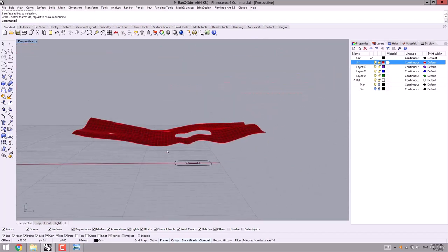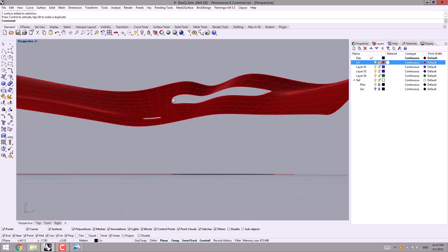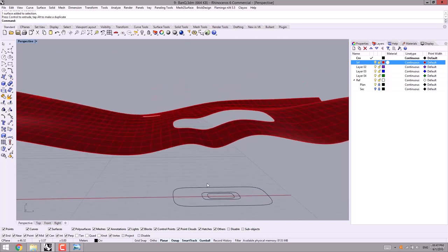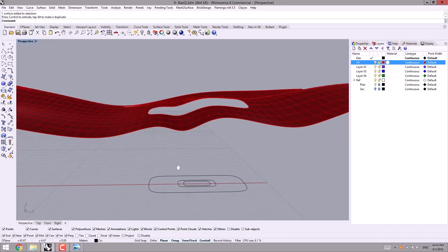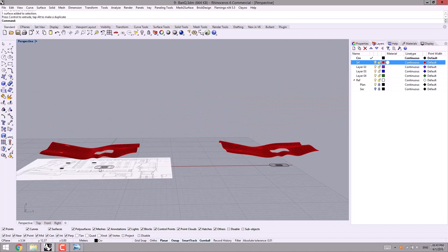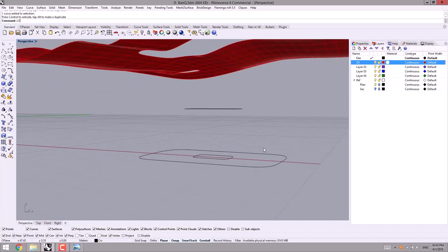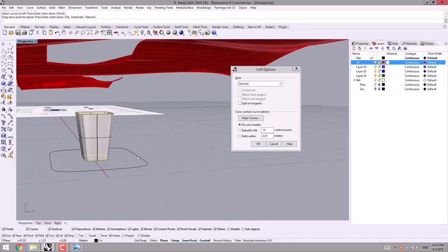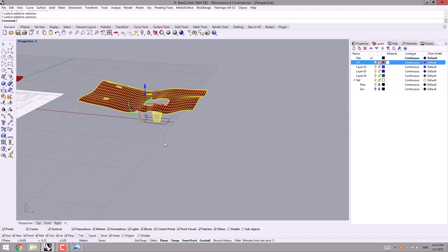Since I'm going to explain a topic for you, here we're going to create a surface at this part, which is going to start from the surface smoothly and then reach the ground. Here I'm going to use different kinds of methods, and then we're going to choose one of them for moving the process forward. So for instance, I select the exterior curve and then I move it upwards, and then I start the loft command. I select specified. So we model the base of the column.